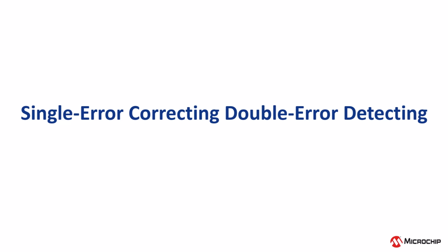These checks are done during any read cycle, so the user doesn't need to worry about enabling or instantiating this feature. However, it is up to the designer to configure how a system responds to certain conditions, such as when an error from memory is received. This system can repair single-bit errors in user data and detect, but not correct, double-bit errors or errors in the ECC address, which makes this ECC protection single error correcting, double error detecting, or SecDed for short.